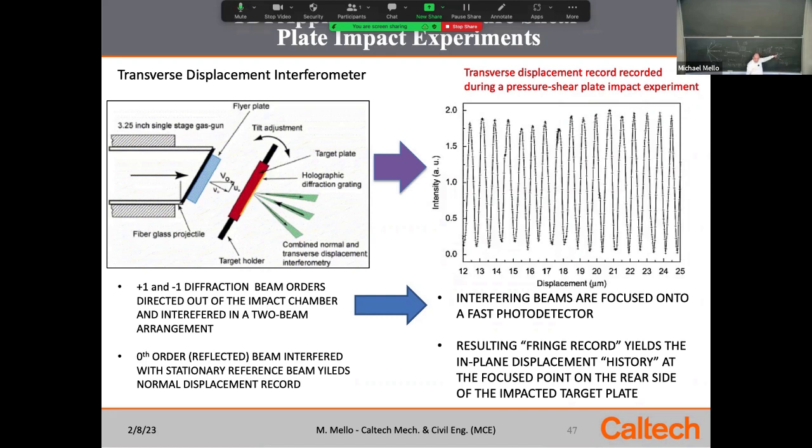And your sensitivity of this interferometer, since it's d/2, say micron per fringe, means your surface has moved by an in-plane amount that much. It would be 1/1200 in this case, because you're dividing that by 2. So the sensitivity of this interferometer, meaning how many microns per fringe that you record of in-plane motion, would be d/2, and that ends up being 1/1200 micron per fringe. Okay, so the pitch of the grating dictated that.